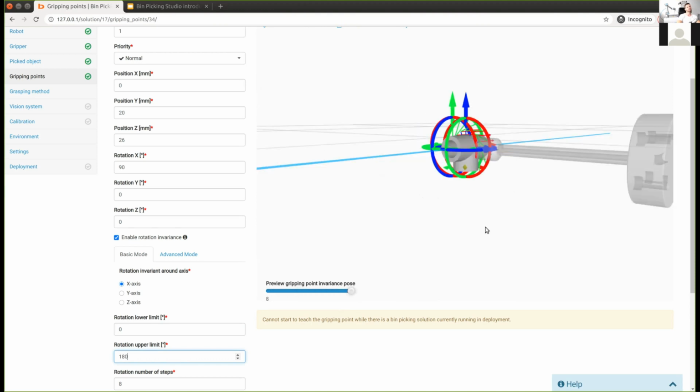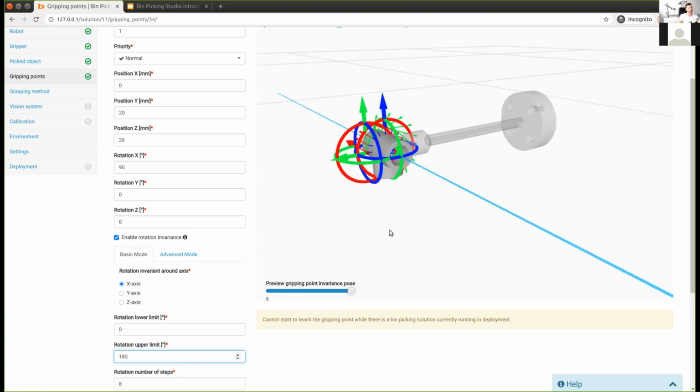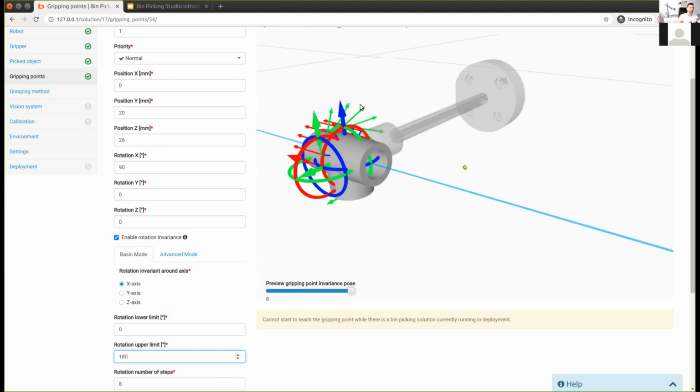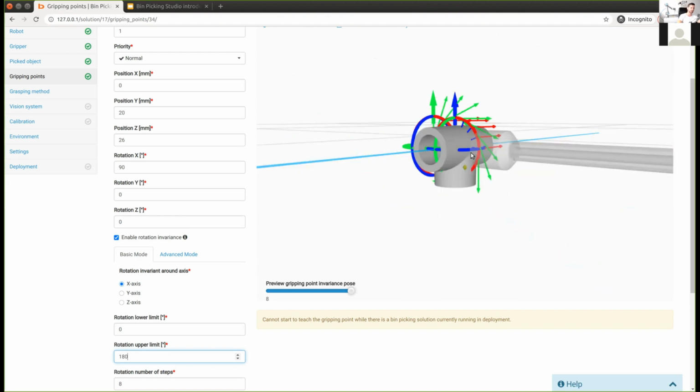And yeah, it looks good. This is something I would like to have in my setup, but also I see a problem in here. As you can see, there is a small opening or something in here, and this could make a leakage of the gases into the gripper.